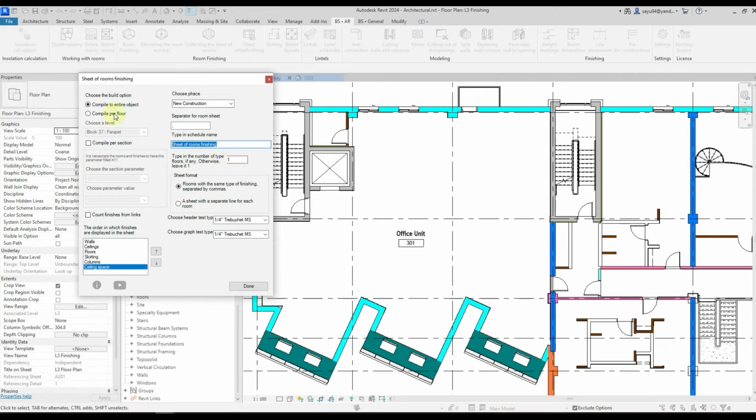Next, if you're doing some kind of typical floor, in the model, you model the finishes on one floor, and yet you have typical floors within your building in multiple units. So, for example, a facility is a premise where the finishes are not changed on the floor. So you can model the finish only on the one floor and then select that floor. In our case, I'm not going to select it, but here is where you can specify the number of typical floors.